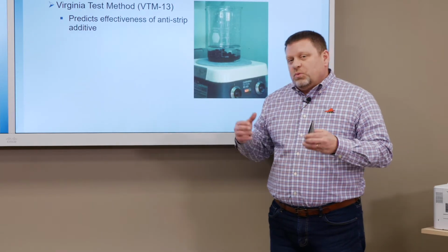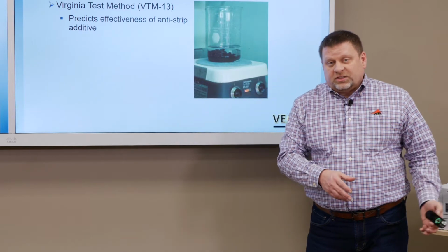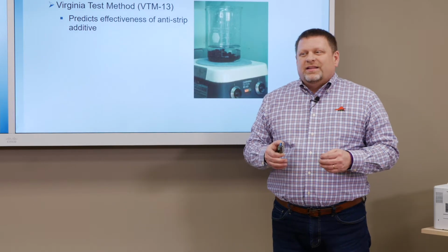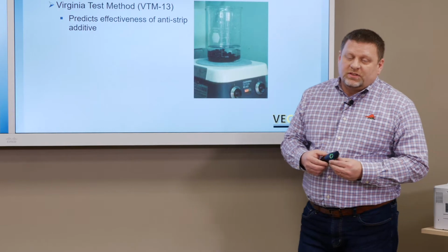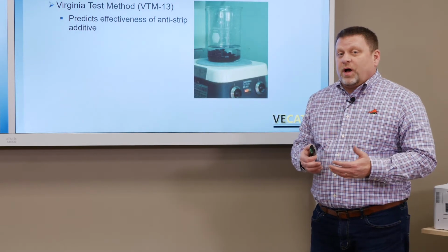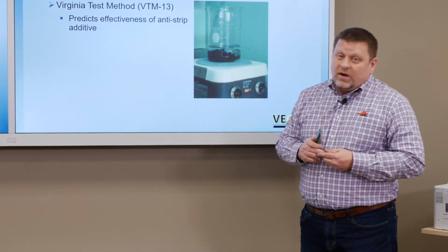What I recommend is when we took our plant mix sample, where TSR samples come from, is that we do one more quick test that provides you as a technician, a mix design technician at your facility, something that gives you a quick indicator if stripping could be a problem in your mix. And that's the old-fashioned boil test. Boil test's been around for a very long time.